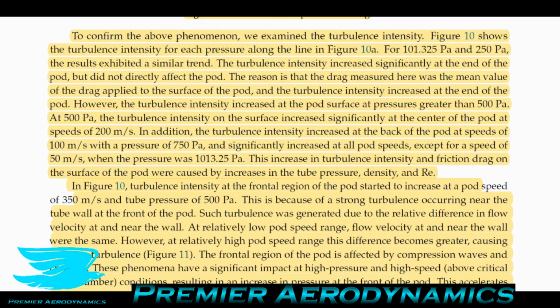And that's because the turbulence intensity is effectively just how non-uniform the flow velocity is. So you might have one point where the velocity might be 20 meters per second, right next to it might be 40 meters per second. So that's a huge difference, and that's going to create a very big disturbance in the flow, which can trigger turbulence or a breakdown to turbulence. So that's how turbulence intensity can affect the flow in a nutshell. If you want to know more, check out the other podcast that I mentioned.